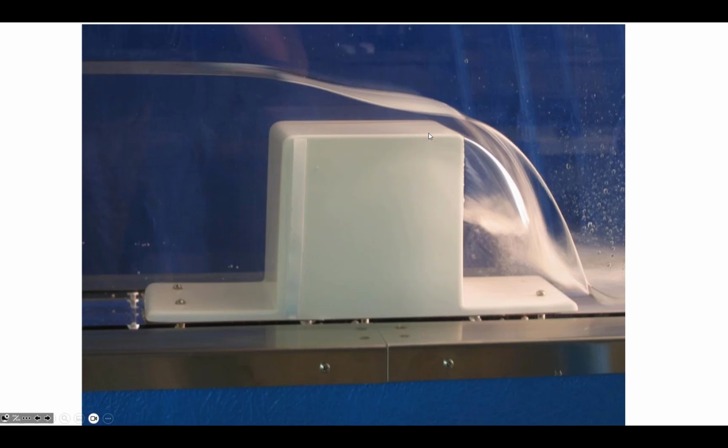So at the critical depth. Now this is a relatively narrow broad-crested weir. It's not very long in terms of the distance of the flow. So there's a little bit of drawdown both from the upstream side and the downstream side. So where is the critical depth? I think what you'd usually see is about the depth halfway in the middle. Before the drawdown starts to happen, you'd measure the critical depth there.